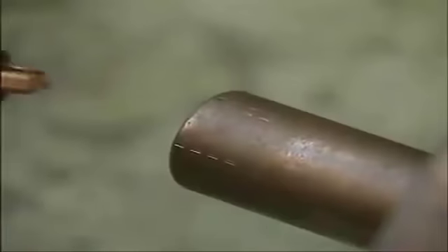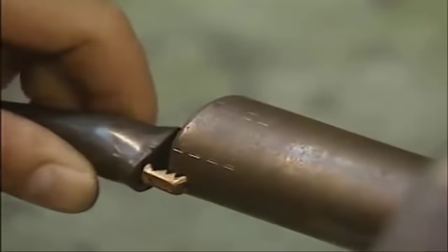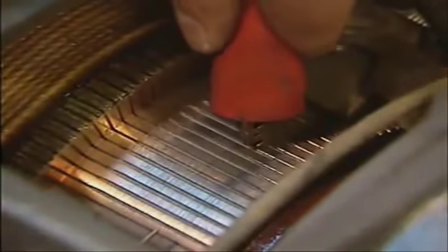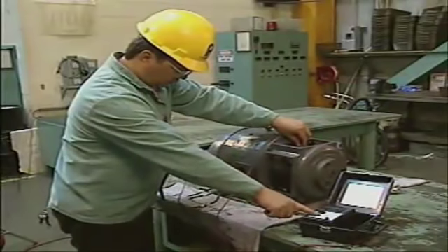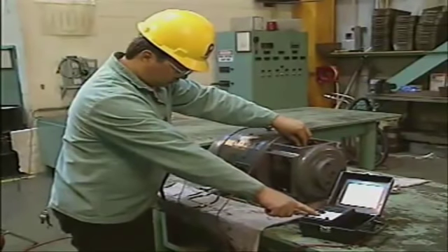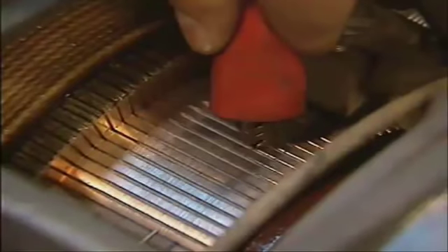To do this, the electrician attaches the meter's ground lead to the shaft of the motor and holds the meter's line lead against the commutator. The electrician then operates the meter, and this time it indicates a normal resistance reading for the armature. There is no ground in the armature circuit, so the entire armature assembly can be eliminated.